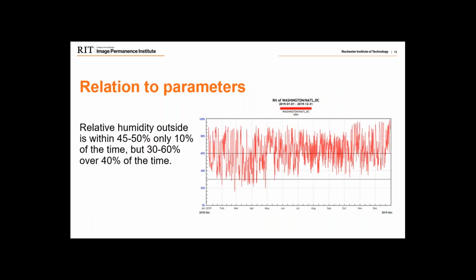So kind of driving this point home a bit, looking at relative humidity. Our goal, we recommend to a lot of people staying in that 30 to 60% range. So here we have the outside air for Washington, D.C., for a full year. So you can see its range, its ups and downs. If we were bringing in that outside air, then you can assume, again, we have to dehumidify here and humidify here. But I also want to make a few points to this.